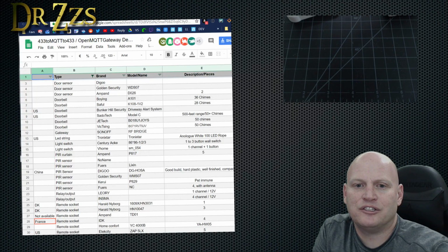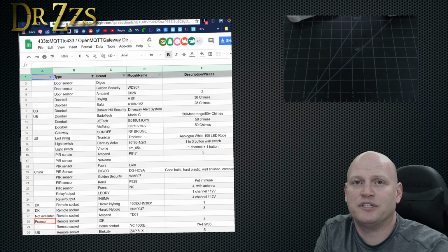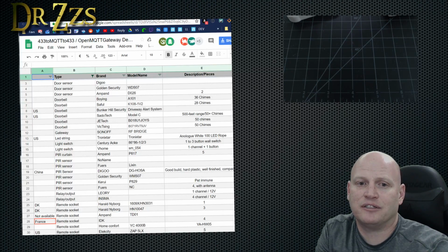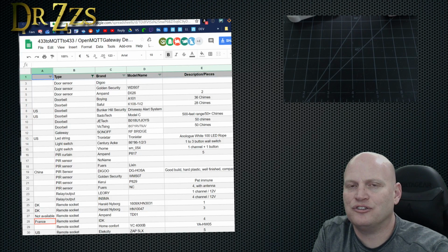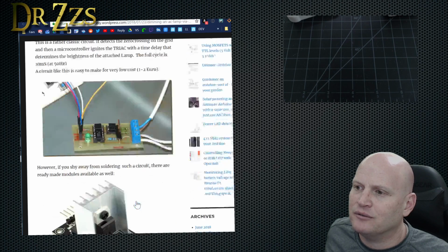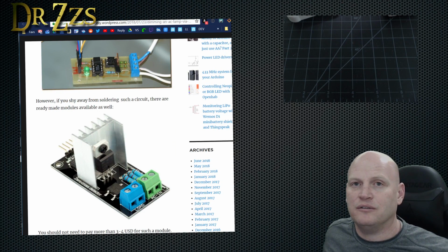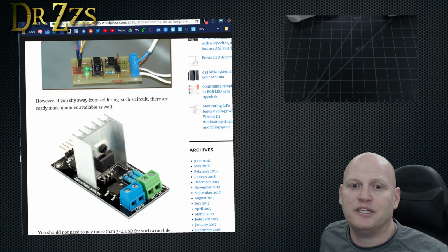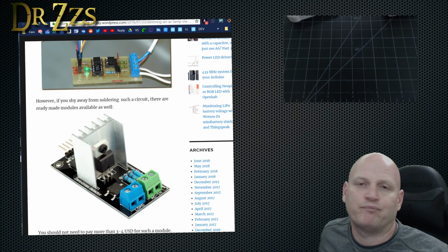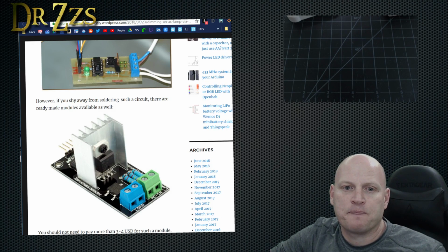Any suggestions on a dimmer for a hall light set? What kind of light, Jack? First question, right out of the box with dimmers: is it LEDs or is it incandescents? Because that makes all the difference. And then either way, I guess it's a module, kind of like what I showed here. Something like this. There are just different modules. You can get one that's for incandescent bulbs, and you get ones for LED bulbs, and it depends on which kind of bulbs you're trying to do.